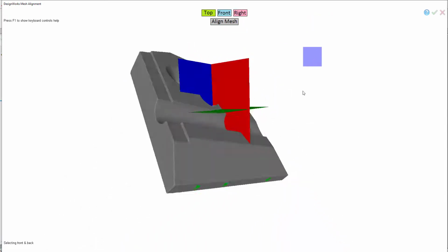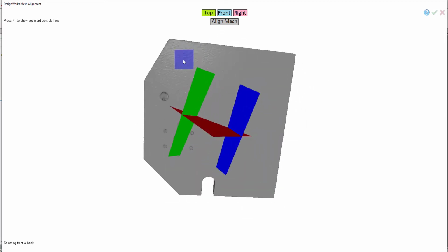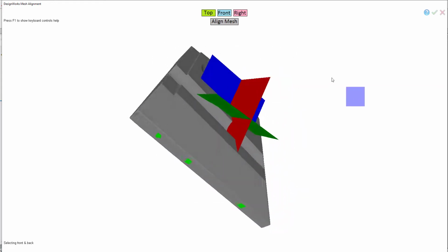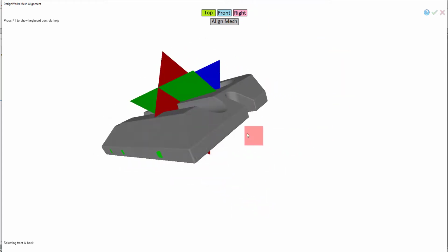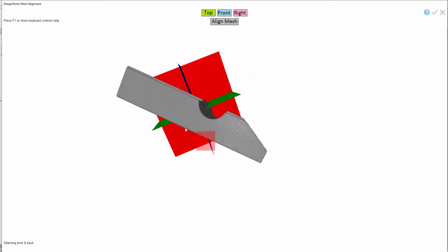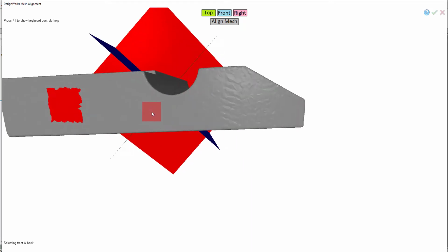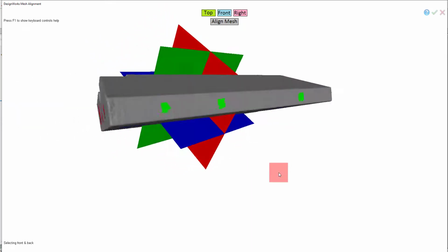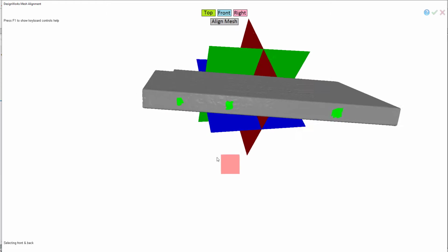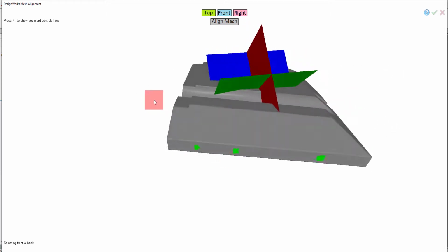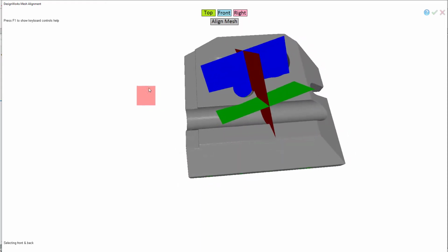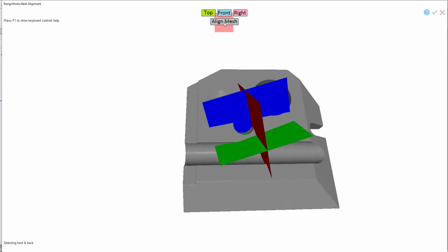I'm going to say my front is going to be on this part down here. Remember, this is like identifying the SolidWorks front plane. And then for my right side, again, you could paint either over here or over here for the right. Our goal is to make the work coordinate system, this would be your front, your bottom, this would be X and Y. So by painting those like that, we can say align mesh.